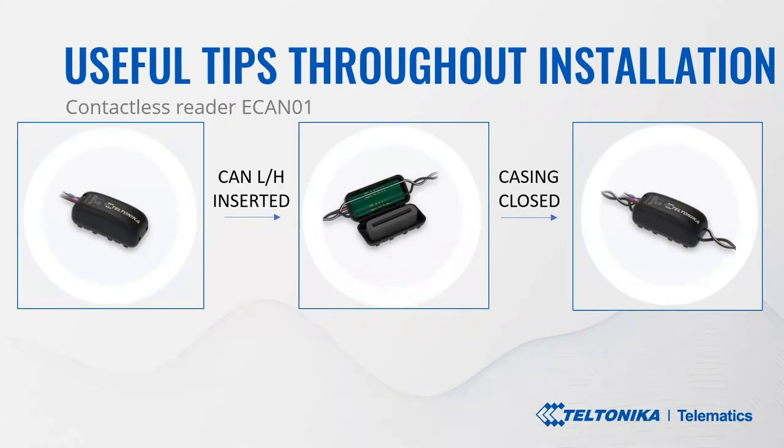However, there is a single disadvantage of this type of connection. When using contactless adapters of any kind, it is not possible to read specific parameters or send request messages to the CAN bus. Therefore, the application with units such as CAN control is not convenient, because you will not be able to use the unlock or lock features.